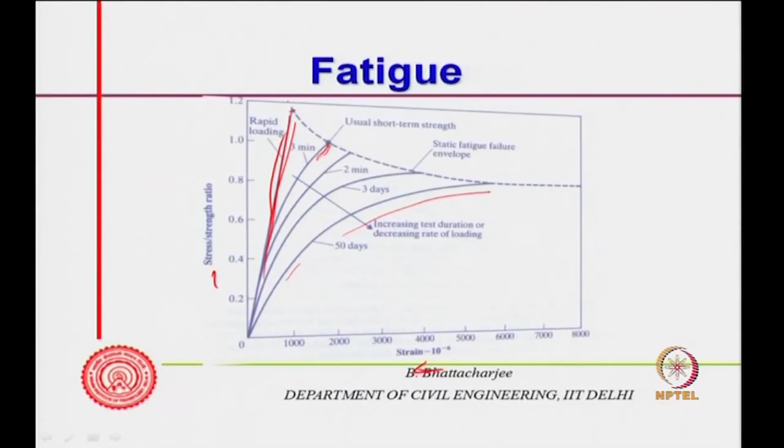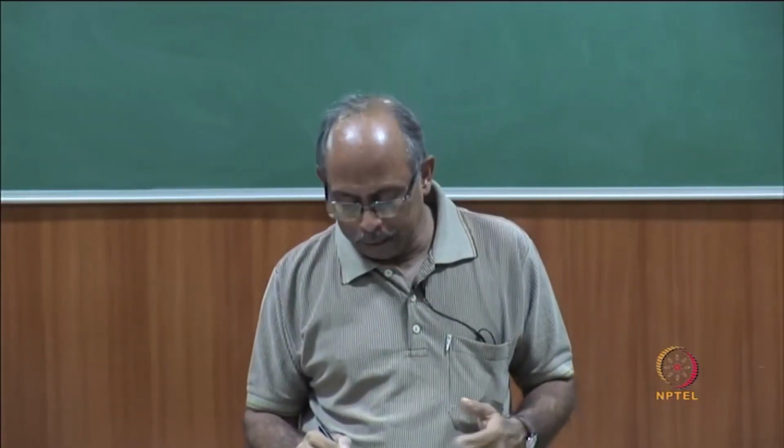not in terms of a strain controlled situation. So, what will happen? With very rapid loading, the micro cracks would not form, but suddenly there will be a sudden brittle failure at some higher load. So, it fails somewhere there. But if you are loading, let us say, 3 minutes up to failure, which could be the case in static monotonic loading, it will fail somewhere there, not showing much deformation. It will show this if you have a strain controlled situation. So, a kind of what we call strain softening would occur. As the strain increases, the load it can carry is lower.